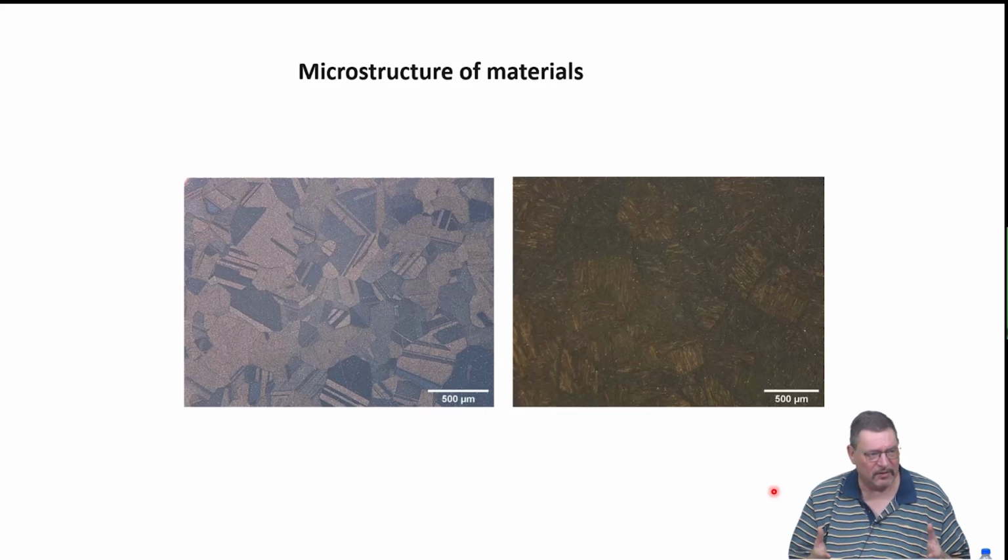We will see later on that if you go to the transmission electron microscopy level, TEM, that things might be different because the defects of the crystal structure, dislocations, twin boundaries, and so on, are normally found in higher abundance in metallic high entropy alloys as in conventional alloys.